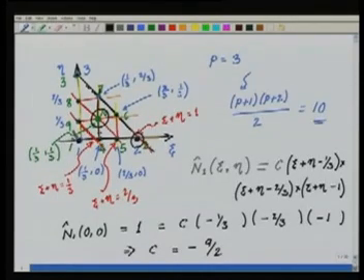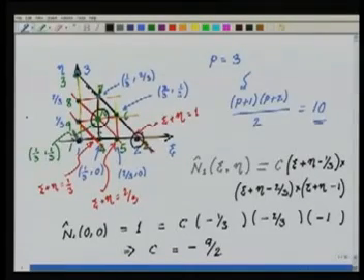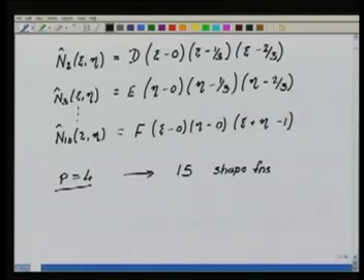So 10 is called an internal bubble function, while these edge functions, if you see, they are going to be non-zero only in the 2 elements which share this edge. Okay, so these are called side bubble functions. And while the vertex functions, well, they are non-zero in all the elements which have this vertex as a common vertex. Okay. So if I have to do the p equal to 4 case, let's go ahead and see how we are going to do it.